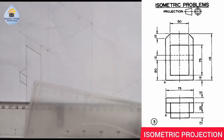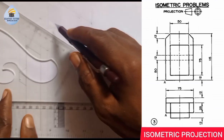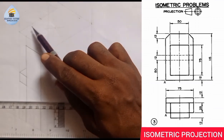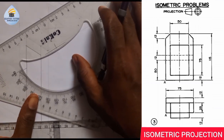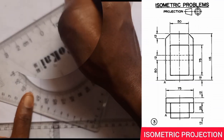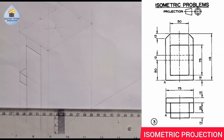So with the help of my T-square and my set square, I know that this is the center point here. I don't want to draw a straight line, so if I don't draw it, this is the center point of that line. So since the thickness is 50, I'm going to measure 25 to the right and 25 to the left. So when I place it this way, I'll measure from 0 here. Can you see that? And I'll measure 25 to the right and also 25 to the left. Right? And look at what I want to do here.